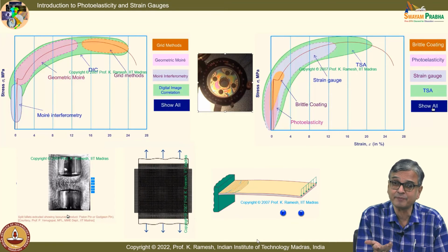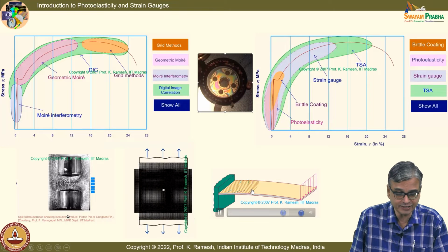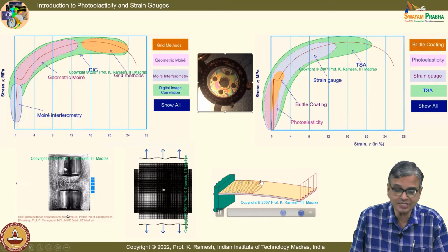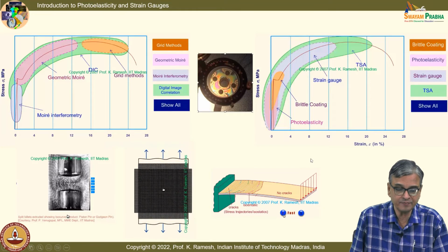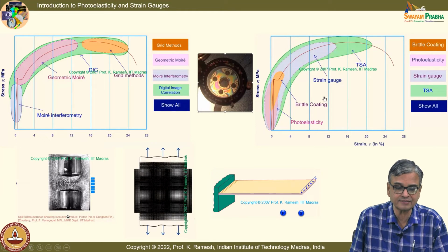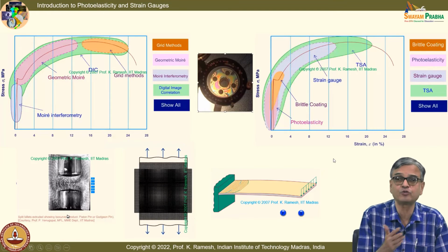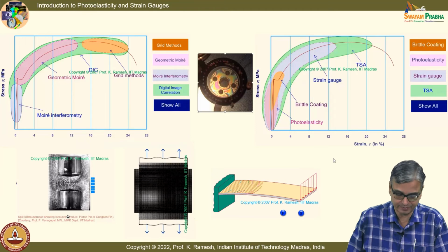Here the crack is the information. The crack shows the material fails in a brittle fashion. So, you get contours, and when you draw the tangent to them, you get the principal stress direction, fine. And a general purpose analysis is possible with a strain gauge, but for special applications you need to go for an appropriate experimental technique for strain measurement.